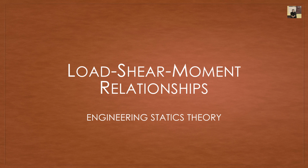So what we're going to do is introduce a super secret to you guys. And you guys probably picked up on this. Again, you guys are the smartest students I know. And that is the idea that the load, the shear, and the moment are actually all related to each other very nicely. If we know one, then we can figure out the other, and if we know that one, then we can figure out the last one. How does this work? Well, if I know the loading scenario, which is something that will always be given to you, so that's always good, I can easily figure out the shear. And if I know what the shear is, then I can easily figure out the moment. So this is going to be a very quick way to solve for shear force and bending moment diagrams.